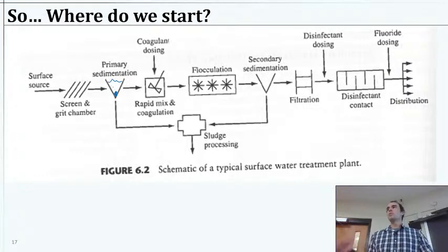Now, the distribution system itself, we tend to consider as a part of our treatment because we design it so that it keeps enough chlorine to prevent any pathogens from repairing themselves or from entering from maybe a leak in our pipes. In fact, one of the reasons we keep high pressure in our pipe systems is to make sure that if we do have a leak, because it's going to happen, the water is forced out and not let in.